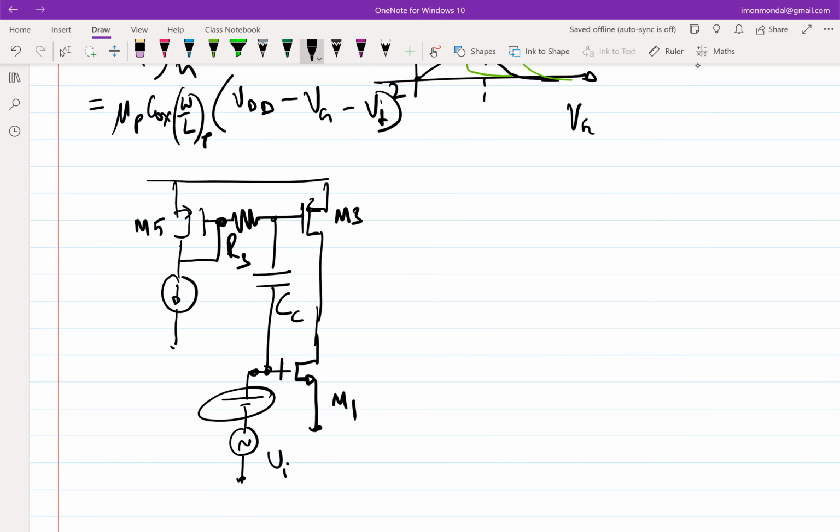Okay. So at the signal frequencies, if CC is large enough, then both gates of M1 and M3 are seeing signal swings, but independently you can set the current through M1 and M3. It's a constant current bias. Okay, so this is another topology that is often used, but this cannot be used at very low frequencies because you have a capacitive coupling. So at high frequencies, sometimes these types of circuits are also used. You keep constant current and still get the benefit of double the GM.